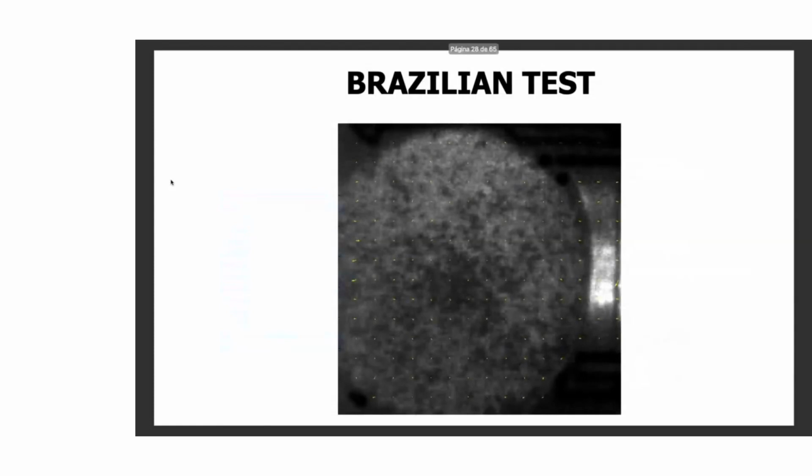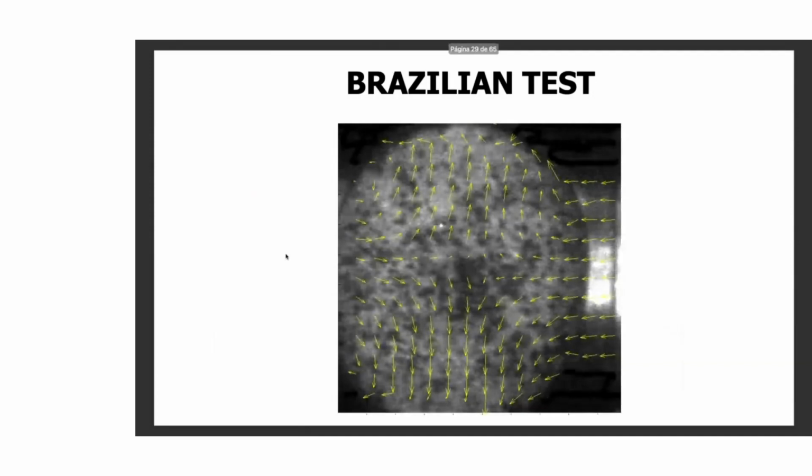You get the curved anvil, which we can see to the right hand side here. Here is the sample, and as we squeeze in, we get the flow pattern showing the motion away from the system, and from this we can look at the Hopkinson bar stress strain output and determine the shear strength of the material from that output.